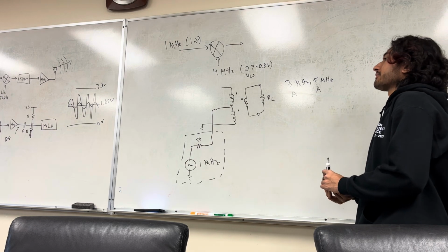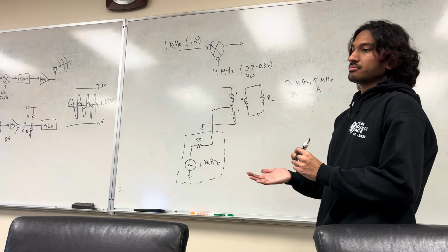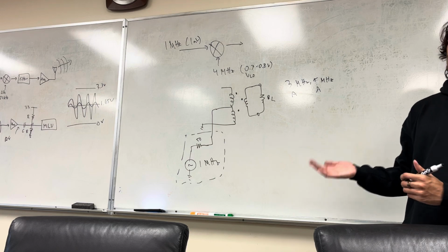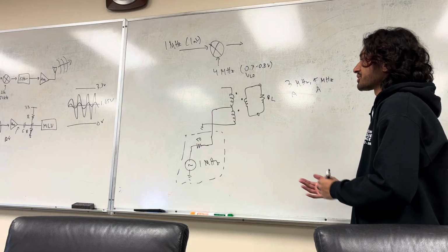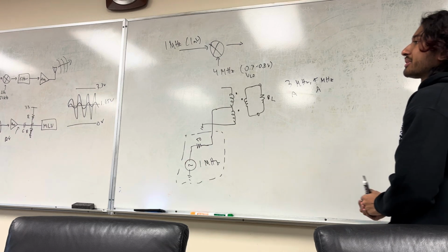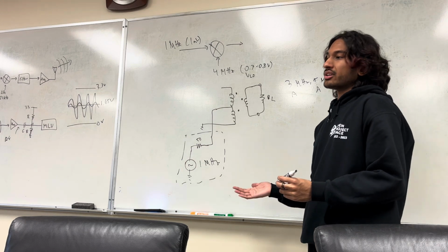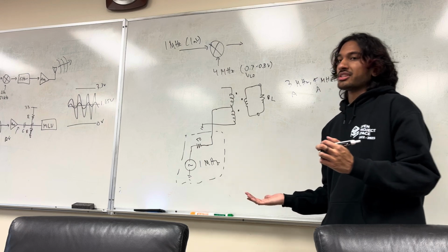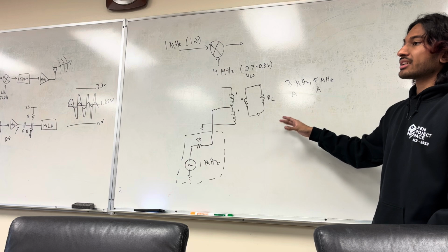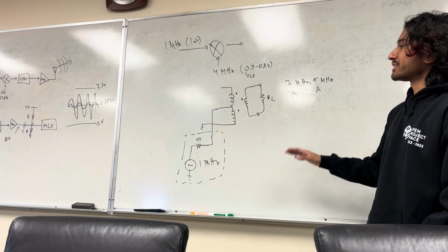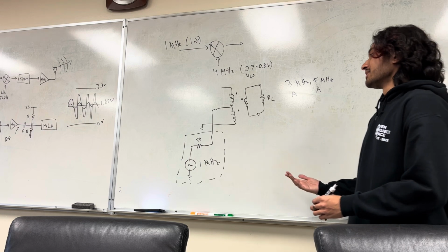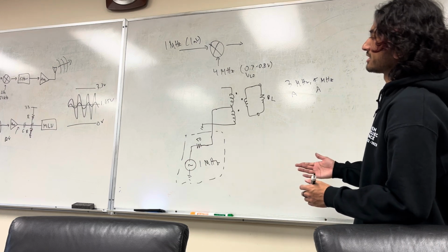However, if we have a very strong signal leakage, what happens to our system? The buffer doesn't do too much to isolate the two to make them independent. So we have to move to something called a T-attenuator. And as the name suggests, it's a type of attenuator. It's just going to shrink the magnitude of all our signals that go into it. So it's not a frequency dependent attenuator. Effectively, a resistor is an attenuator, right? So that gives us some basis there as to how we can implement it.